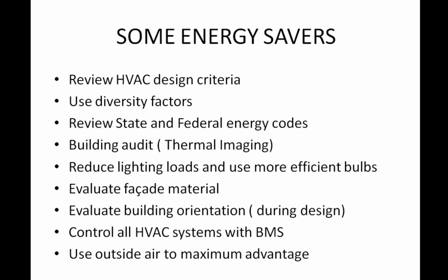So, some tips in terms of energy savings when you have discussions with your developers and your architects and engineers, and you want to create a very inhabitable, livable, and marketable place nowadays. You want to show energy savings and Energy Star criteria. So take a look at your HVAC design, see what you can do as far as increasing ways you can save energy, using higher diversity factors when you don't expect full occupancy at all times. Make sure you're meeting all the new state and federal energy codes.